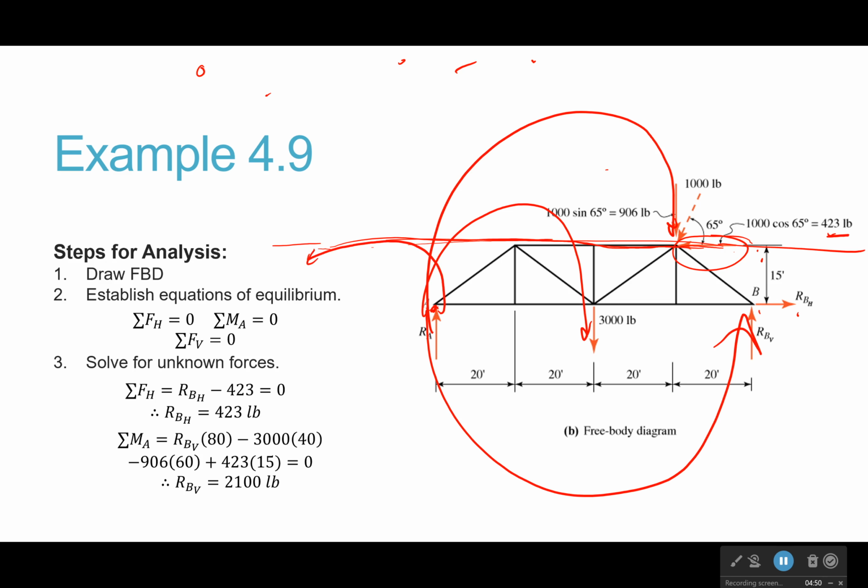So if we look at this, which one's going counterclockwise? Like that positive, that one's counterclockwise, that one's counterclockwise, and these two are clockwise, they'll be negative. So for any of these ones that you can't use this method, if you're using this method to help yourself, just draw the line of action of the force that's got you confused, both directions to infinity, and then you just drag your little arrow line straight over to it, and then turn along with it in the same direction that the force is going.